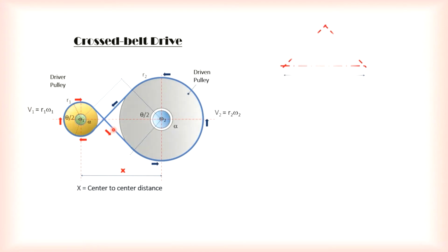Always welcome. So, if we want to find the angle of wrap, in this case here should be your theta. The whole theta should be here. So theta over 2 should be this angle here. Your wrapping angle is from here to here. So don't care about theta or alpha because these are only symbols.